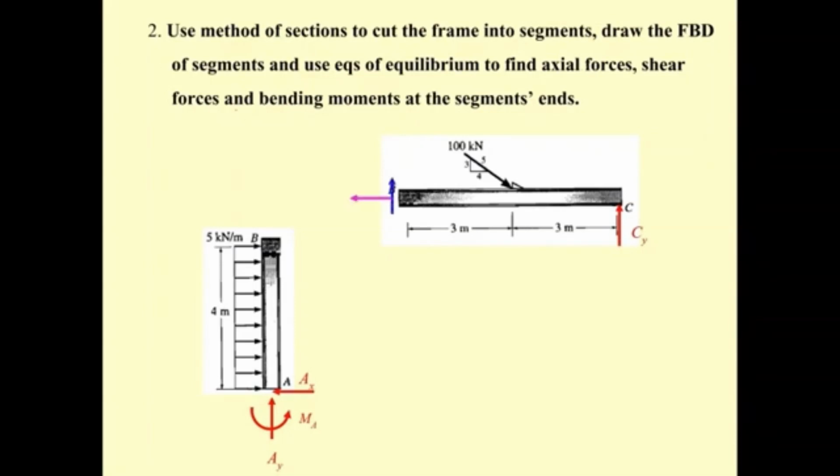The B sub X is the blue, and the pink vertical one is going to be B sub Y. And when you have this kind of connection force, by Newton's third law, you will have the blue in the vertical direction. You may notice the shear here can transfer directly, and also the normal force here will transfer to this directly.